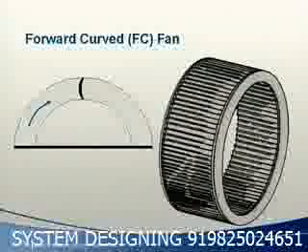These fans are operated at relatively low speeds and are used to deliver large volumes of air at relatively low static pressures. Due to the inherently light construction of the fan wheel, FC fans usually cost less than fans with other blade types and are typically used in smaller systems that require static pressures of about 4 inches or less. But FC fans are usually less efficient than other fan types.